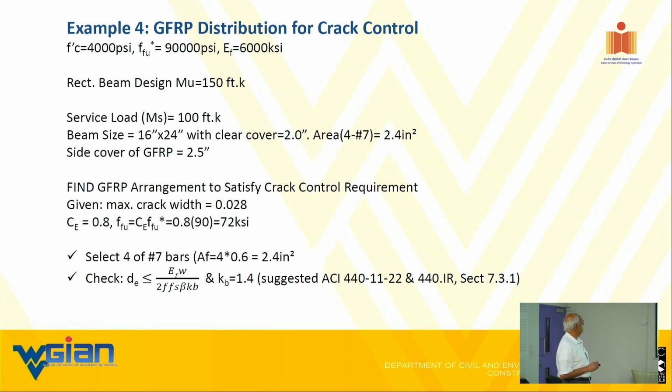And this is a beam, and this Mu is inclusive of your load factors. Whatever we're going to do now, we should make sure that the φMn is higher than Mu. That's the idea behind it.